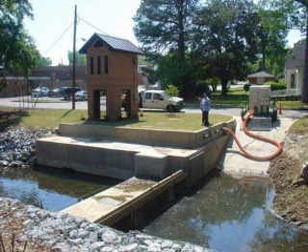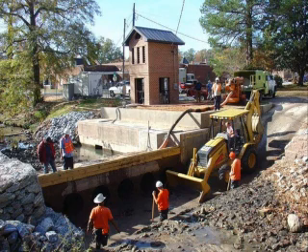Then above that capacity of the filtration system, the flow control bladders open up, and you can see in this picture that before it's starting to top over the wooden weir, the flow is boiling out the back end of those flow control valves. Those valves have opened up now, and the flow is going through those valves. As the rainfall and runoff conditions get greater, the flow goes both through the flow control valves and over the weir itself.